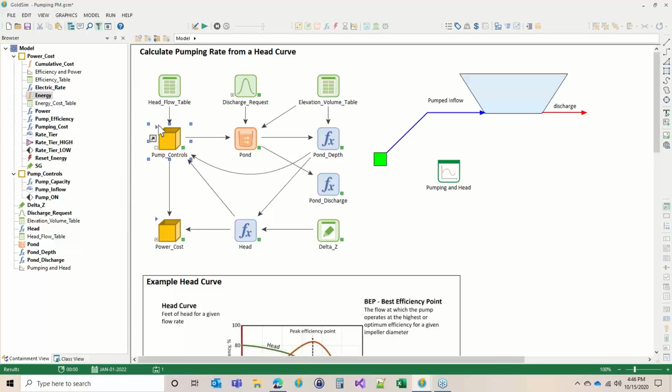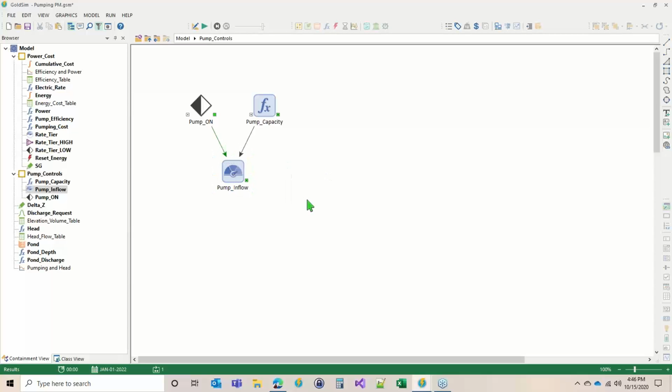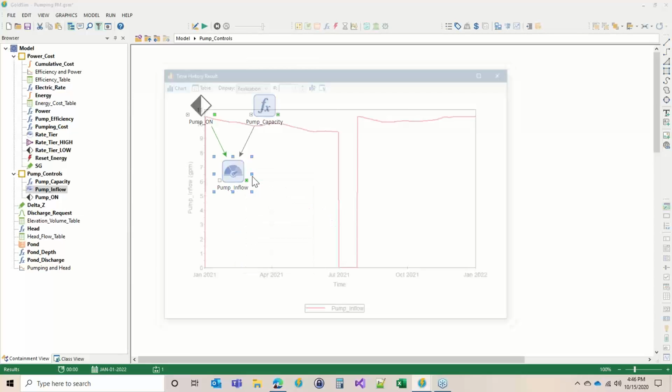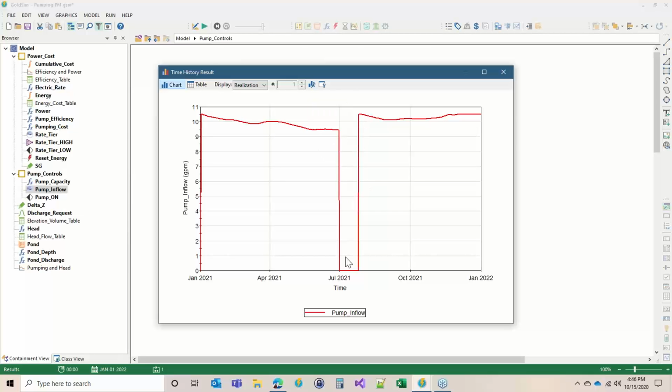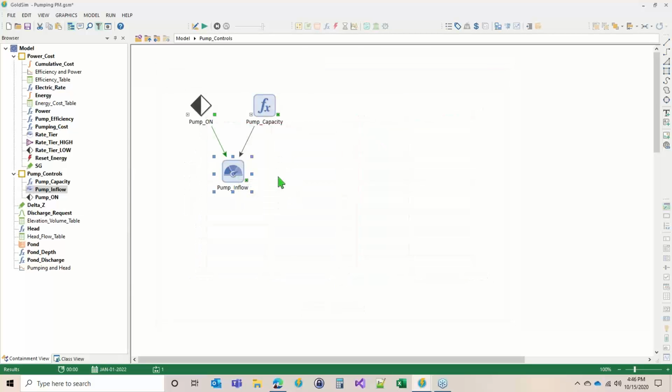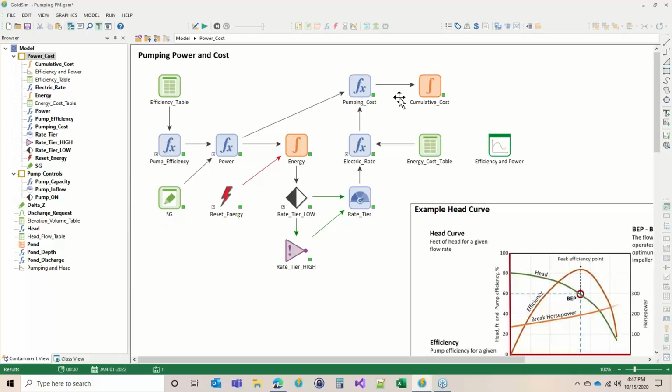One thing about turning the pump on and off is that if you look at your rate structure that's published, a lot of times you'll see a thing called a demand charge. The demand charge, they apply when you turn the pump on. And so every time you see this jump from 0 going up to here, then they would charge you. And so you may want to avoid that. The example that we have on our website does incorporate demand charges. So it's kind of nice. All it does is use a discrete change to figure out, well, first it looks at if it was off previously and now it's on, then it triggers a demand charge, and you add it as a discrete change into your cumulative cost. Just imagine a discrete change adding to that. In fact, I should probably just show you this model instead of just talking about it hypothetically.